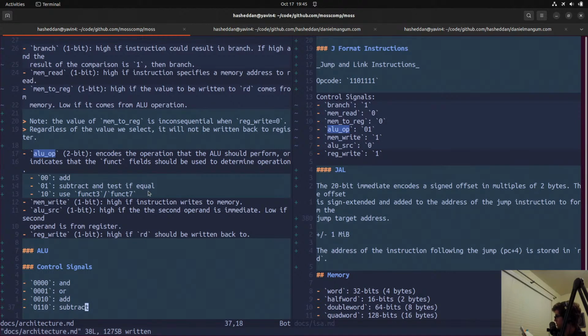There is basically no instruction decoding happening here. The immediate gen goes into the adder. The PC does not require write control since it is written once at the end of every clock cycle. The branch control logic determines whether it is written with the incremented PC or the source target address. So it has a separate control signal at that point, and it's calling it PC source.